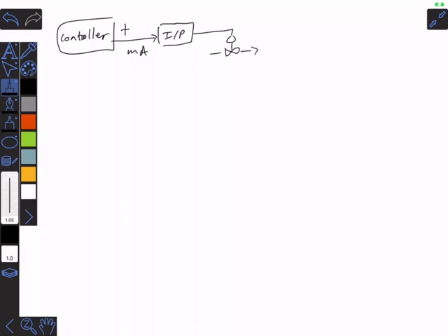But I have a choice of valves. I can have a valve that when I increase the pressure to the valve, it reduces flow. And I can have a valve that when I increase the pressure to the valve, it increases flow. So the valve itself can have a sign.